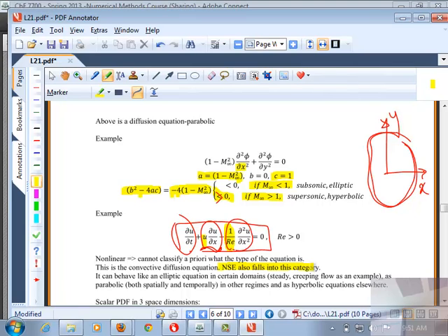What have we been doing all this time? We developed methods for linear systems and apply them to nonlinear systems locally by linearizing, right? So in that sense, the classification for the linear PDEs helps us. This class of methods works for elliptic problems. If this nonlinear problem behaves in an elliptic manner, I can apply that particular method. But the beauty of these CFD solvers is that they try to capture all the behavior in their numerics.